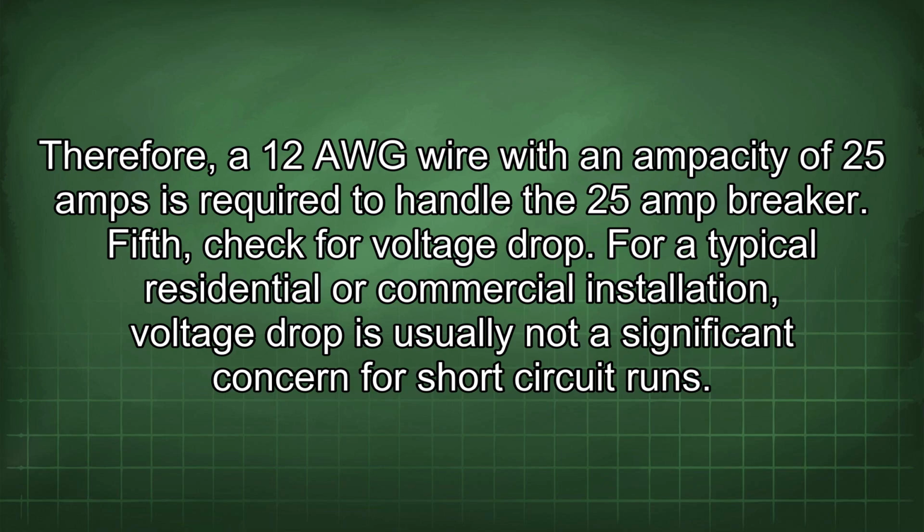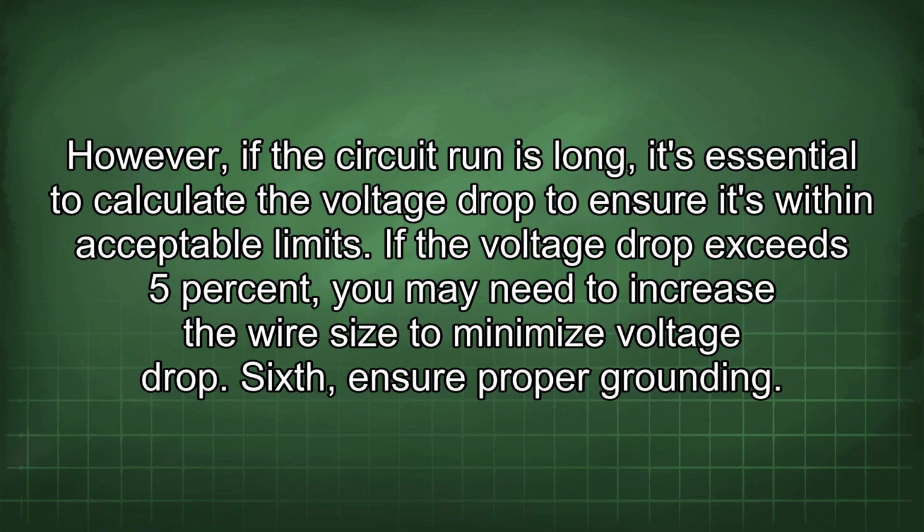For a typical residential or commercial installation, voltage drop is usually not a significant concern for short circuit runs. However, if the circuit run is long, it's essential to calculate the voltage drop to ensure it's within acceptable limits. If the voltage drop exceeds 5%, you may need to increase the wire size to minimize voltage drop.